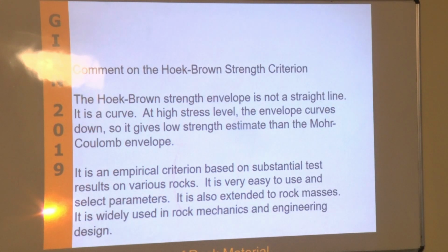If you ever have the chance to meet Hoek, one of the things that he always says is that my worst mistake was to actually write the Hoek-Brown failure criterion, for a simple reason: people are misusing it. They don't understand that you should have a range, not just one single value. If you miss that point, you haven't read my papers, and you don't understand at all what the criterion means.